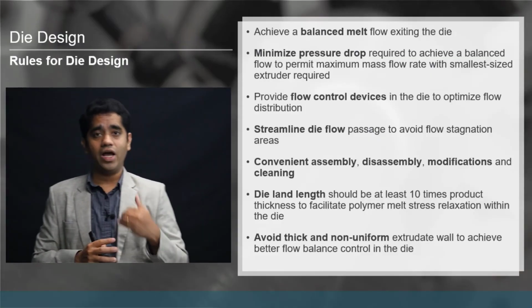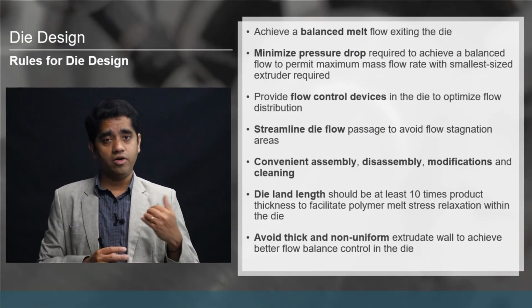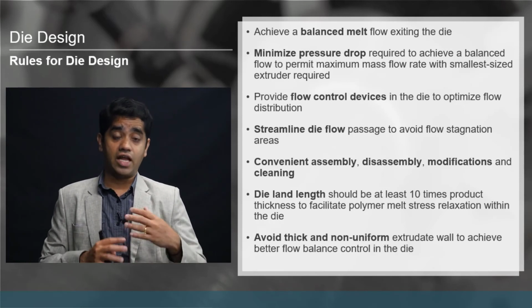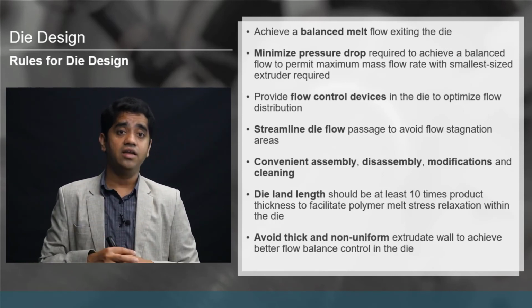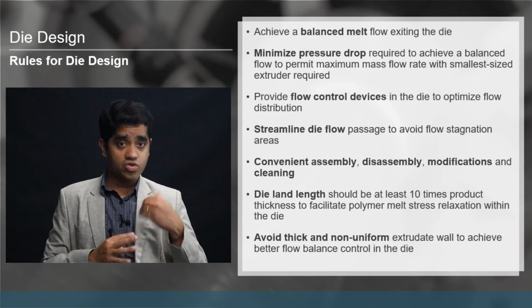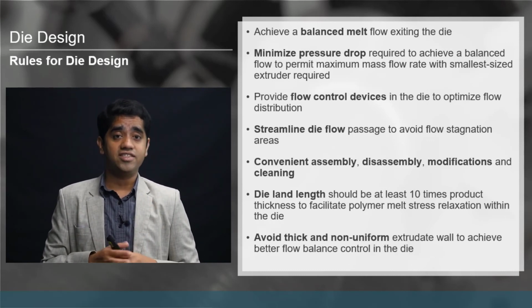And as I talked about, avoid thick and non-uniform sections. In fact, having thick and thin sections within the same product is also going to cause you these kinds of instability issues.